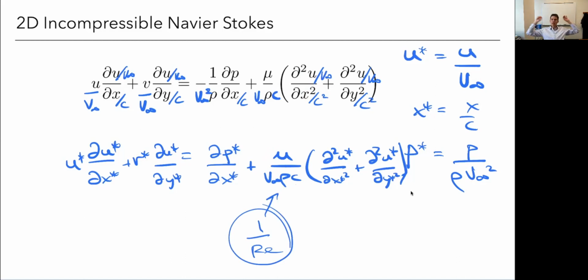In different scenarios, I could have very different velocities or different sizes or different viscosities or whatever. As long as I have the same non-dimensional geometry, right? It's a scaled version of the geometry and boundary conditions, of course. All I have to do then is match the Reynolds number between these two simulations, or simulation and real life, or simulation and experiment. Match the Reynolds numbers, and the non-dimensional flow solution, meaning the non-dimensional pressures and the non-dimensional velocities, will be the same, okay?